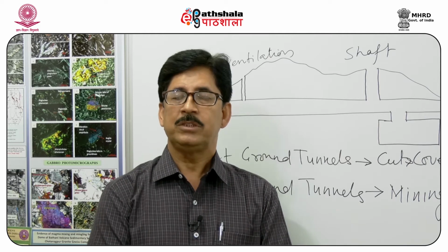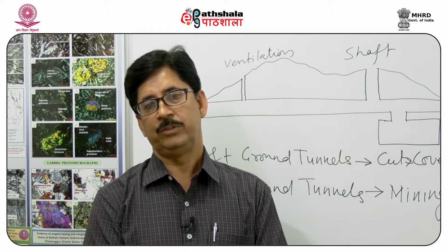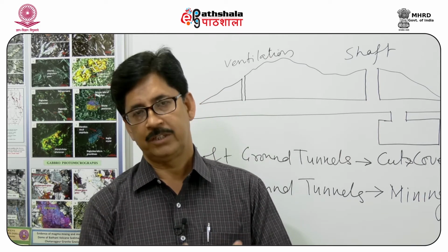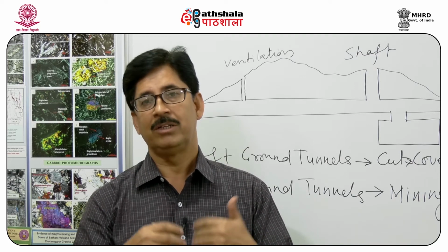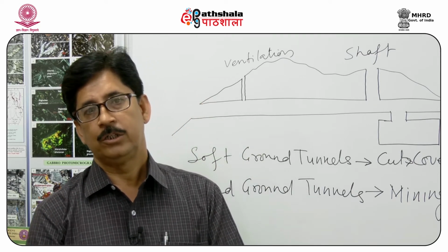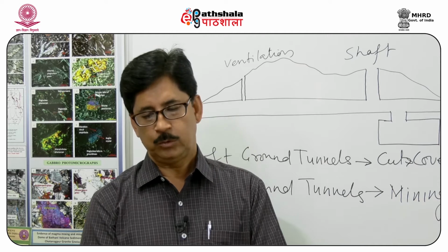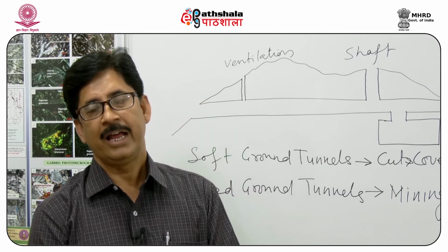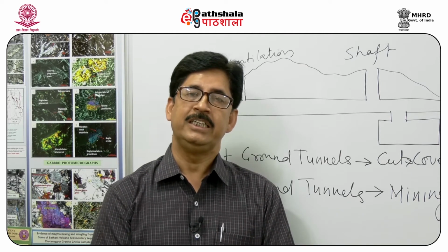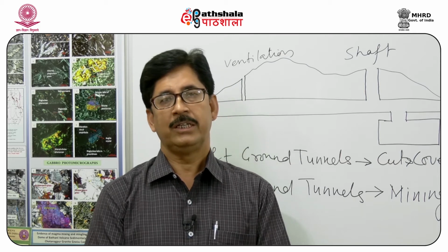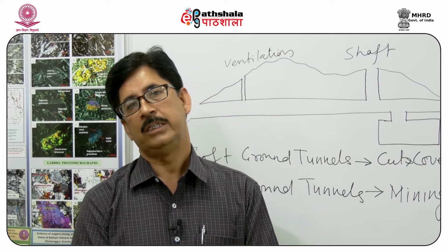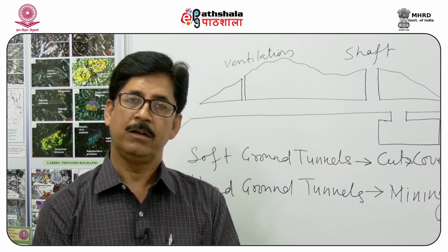We sometimes give time for gases which have been trapped in rocks after explosion, or the gases which were already trapped in rocks, to go out. That is called the recuperating stage. After mucking and the recuperating stage, we create the opening, and then if there is any need of support, we go for installation of support in the opening.